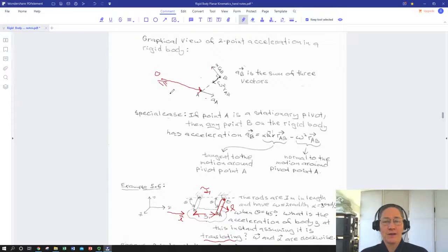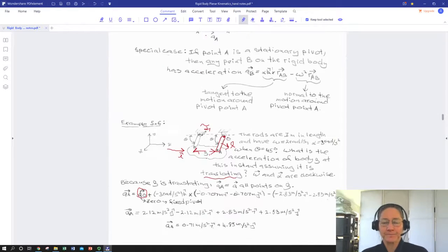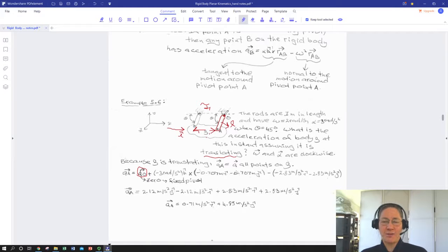Okay, great. So we're just going to keep flipping back. So AP was 0 for that. So now we just need to look at the other two components of acceleration of that rotating bar. So first we can develop a radius vector from our point of known acceleration O to our point that we're looking for, A, at OA. Well, that's just going to be the length of the bar, which we're told is 1 meter.